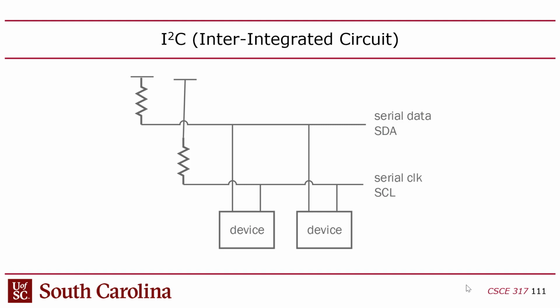The pull-up resistor, where is that? Is that something you have to put on? Usually it's external. Some chips will have it internal though. So you have to be aware of that when you're connecting chips, whether they have an internal pull-up resistor or you're expected to pull it up externally on your circuit board.